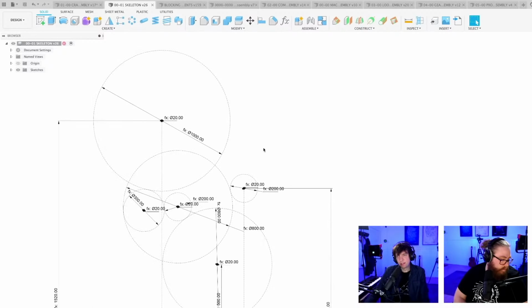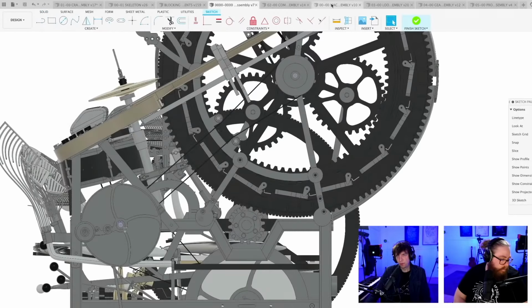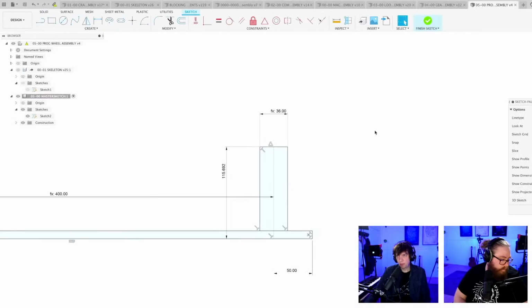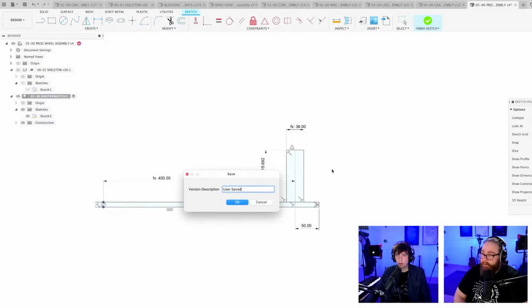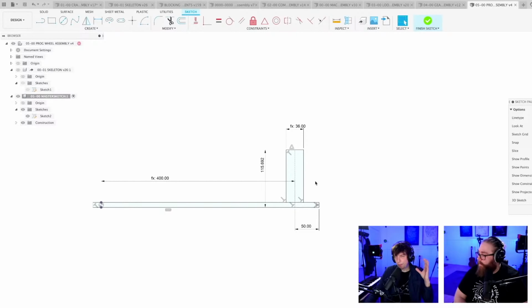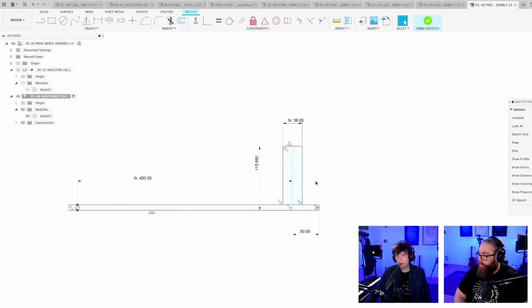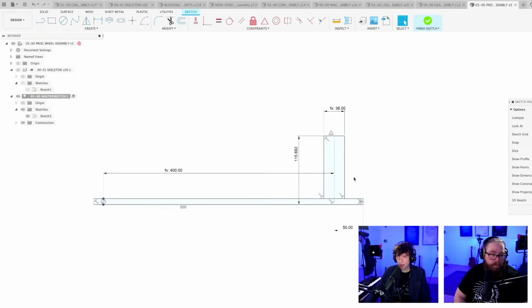And also the belt tension, in my experience, the belt tension is not that easy. Then you either want your shafts to be movable, so you can tension by moving the shafts in and out from each other, which means that you have to have the bearing housings and everything movable. It's a big adjustability issue. Or you have to have a roller that rolls on the belt, and that roller also makes sound. So it's, I don't know.